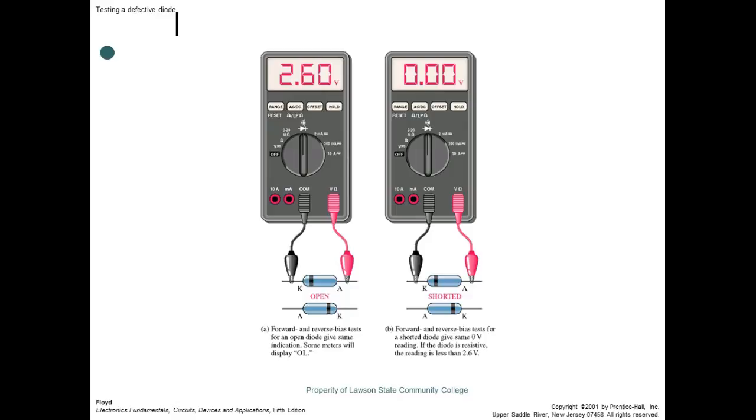And you only lose 7/10. If it's silicon, you only lose 7/10 of a volt per diode. So you got 300 volts or all this voltage to work with, and you got 7 of them in series, then you're only going to lose 2.1 volts. So what's 2.1 volts on 500 volts? It's really nothing.